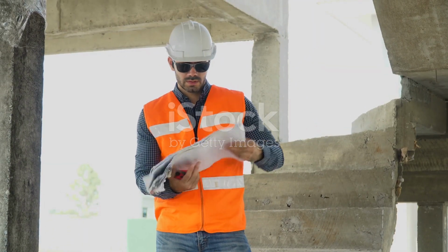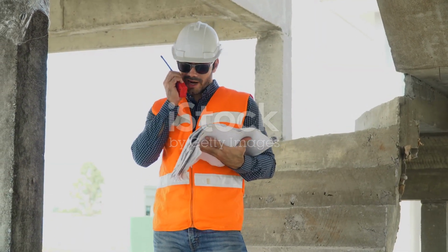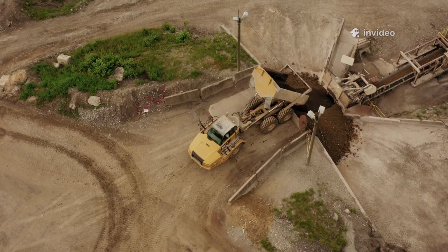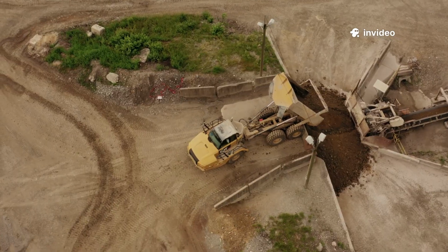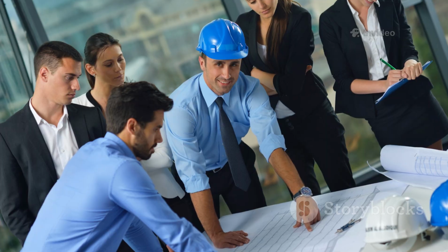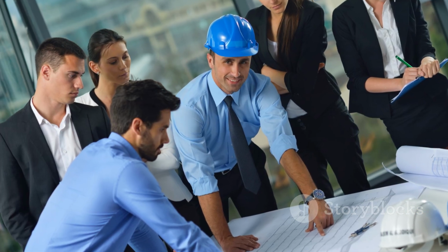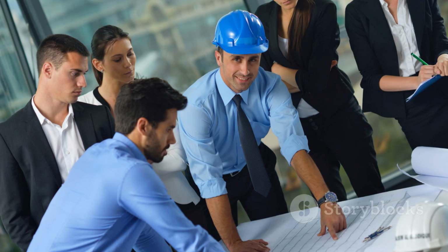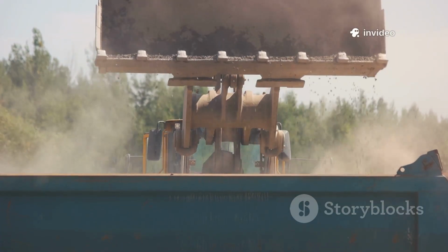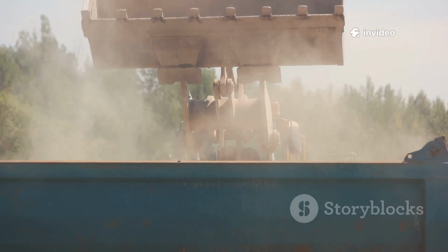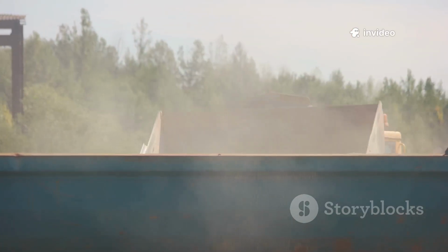So how does the mass haul diagram get used on site? It's the daily playbook for superintendents and foremen, guiding every move of scrapers, dozers, and trucks. Each morning, the team checks the diagram to see which cuts and fills to tackle, and where to send equipment. It helps assign the right machines to the right jobs. Fast trucks for long hauls, scrapers for short ones.